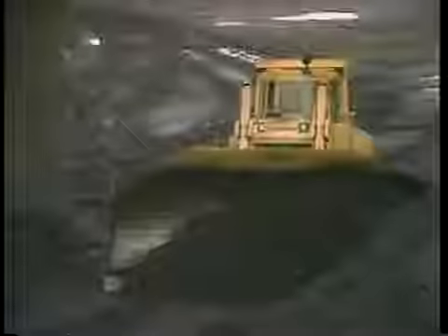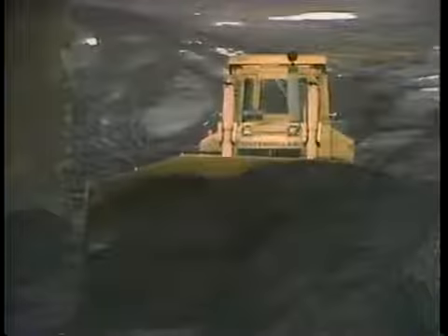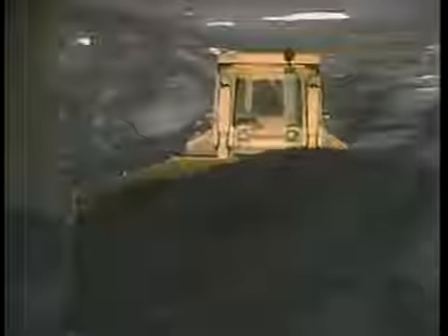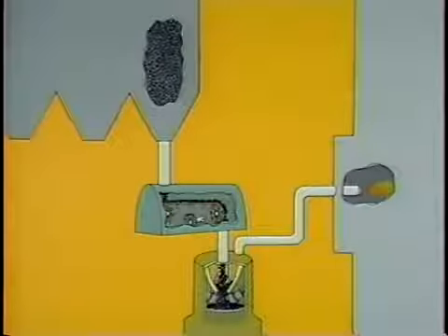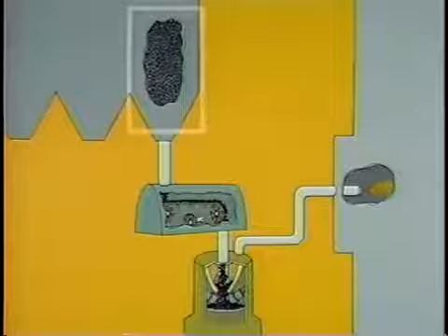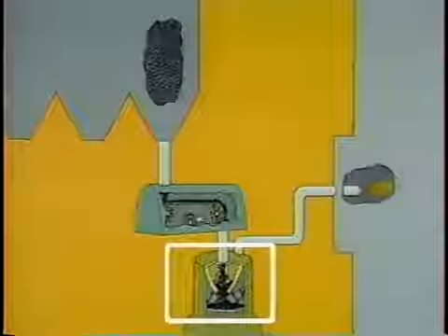In general, coal pile fires are put out by compacting the coal with bulldozers. Compacting eliminates air from the combustion process, and the fire smothers. If coal pile fires are not extinguished, the fire can be transferred from the pile to the coal bunkers, feeders, and pulverizers. How an operator handles fires in the bunkers, the feeders, or the pulverizer will depend on the severity of the fire and the circumstances and conditions in the plant.